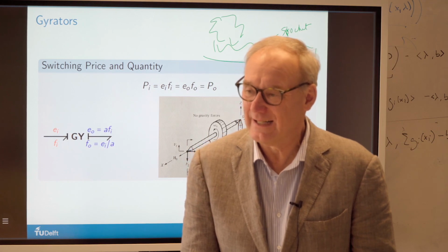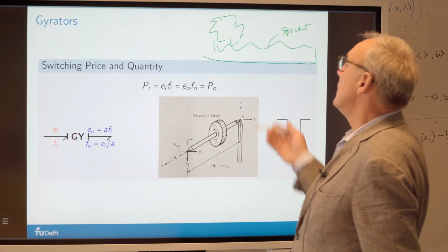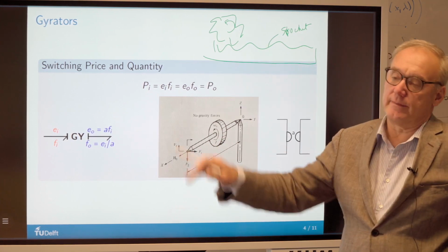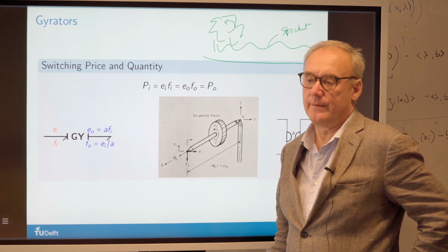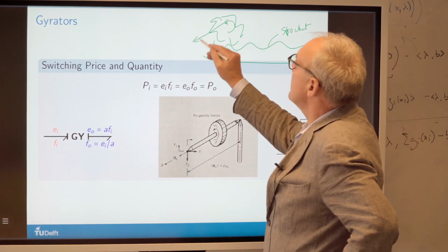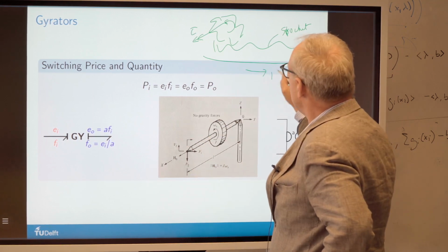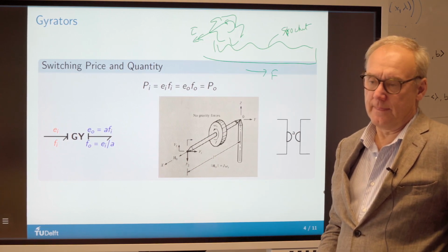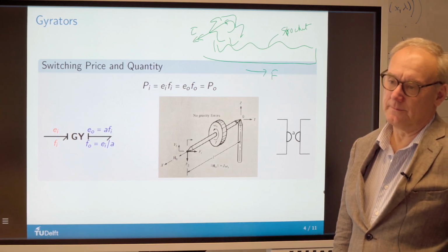In 2D, do we use the gyrator or the transformer? No, what you do is you go from a rotational domain to the linear domain, right? I believe this is also a transformer, right? Yeah, it's a transformer, because you're constrained by the... So it works in the same way: here will be your torque, and your torque translates into a force, okay? You're constrained by the material, so you cannot move at a different velocity than the rotation.